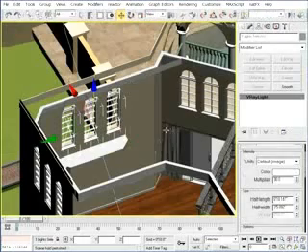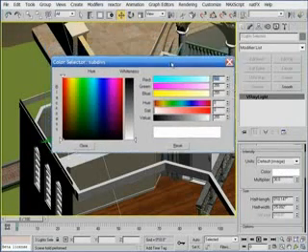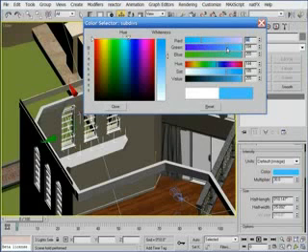Getting back to the interior scene for the Lusso project, for this scene I could use any combination of color and intensity value for the various VRay lights, but I want the light coming in through the window and the door openings to have a light blue hue to it, just like the color of skylight coming in during a midday sun scene. And there's really no reason why any opening in the scene would have a different color to the skylight coming in. So for all the fill lights here, I'm going to use the same light blue color, and simply adjust the intensity multiplier of each light to control the relative variations in skylight coming in.